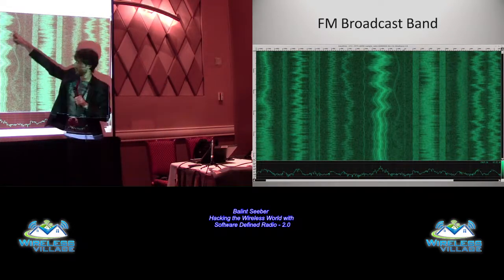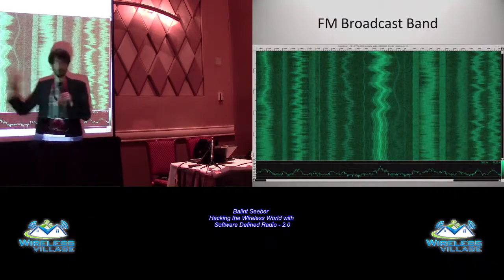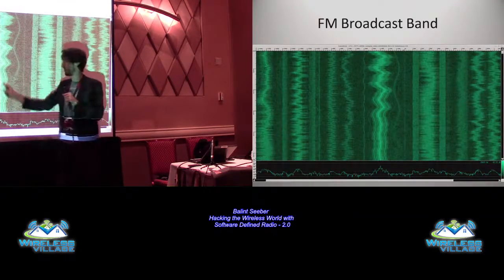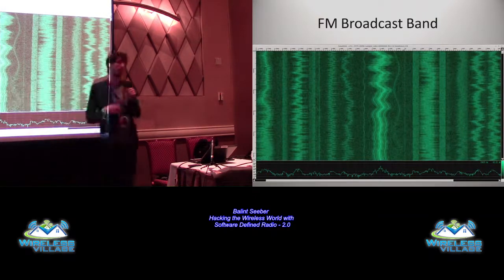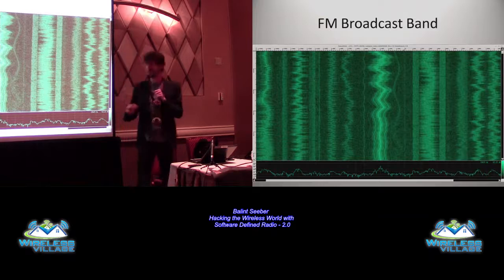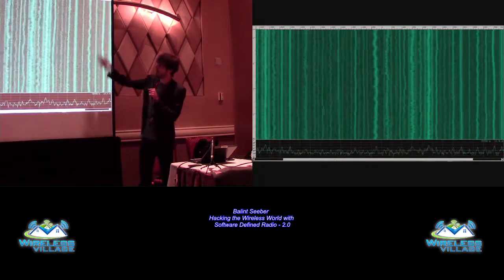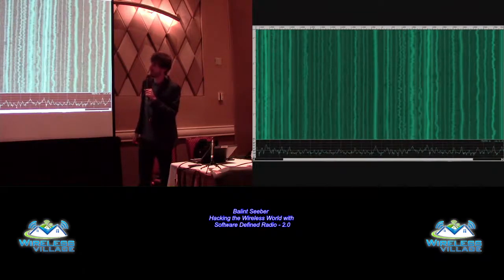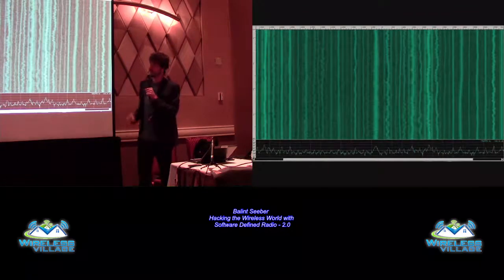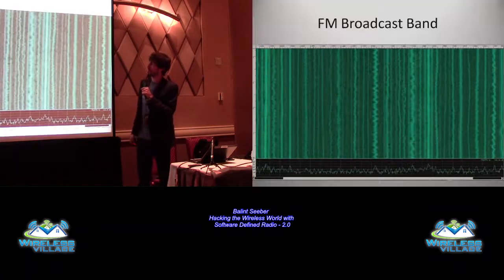So I think here, for example, somebody's actually talking. This is a bit of speech here. See, these are moving much more, so there's probably a lot more modulation going on, but this is someone's speech. And if you also look closer, you can see modulated on there the 19 kilohertz pilot tone, which is used to recreate stereo audio and so on. This is a sort of wider view, but if you look at it in a video, you can see that kind of modulation taking place there. It's a good way to get an idea of how a signal works.